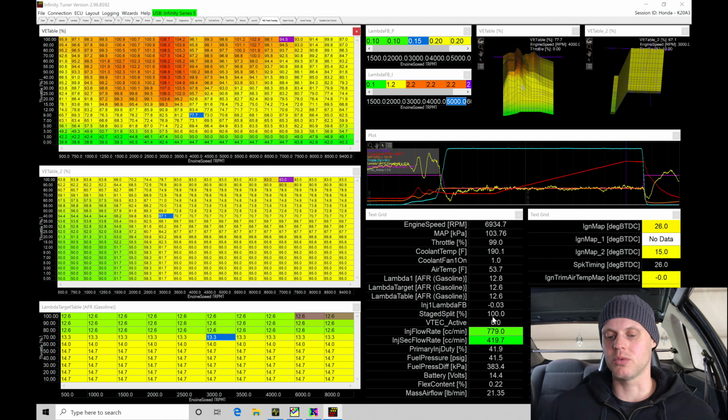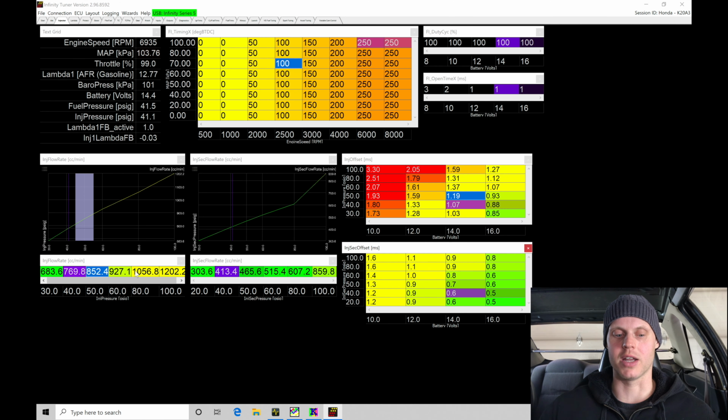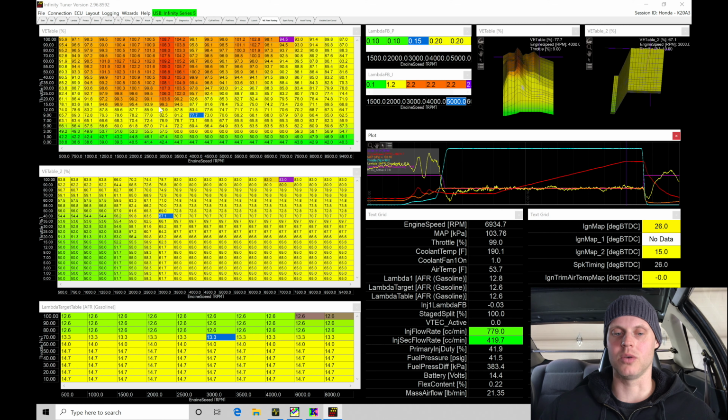If we found that this was really low or really high, and these values were all over the place, we wouldn't have represented the actual airflow coming into the engine, which can be a result of improperly programmed engine displacement or injector data. Remember, we had to go in and start to skew the injector data. I went in from the injector data sheet from Injector Dynamics and I used the values. We ended up having to drastically change these to get our VE values back in line to where they needed to be when we started off our tuning process.